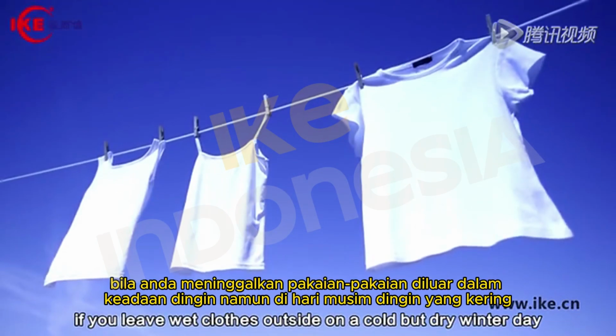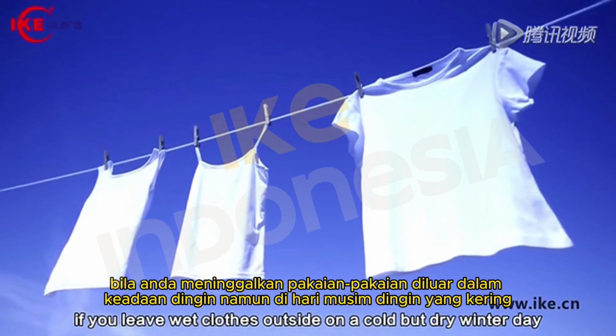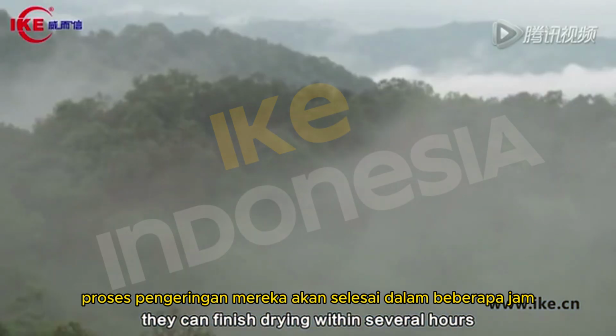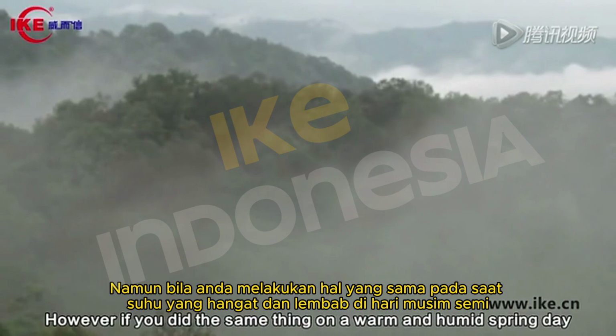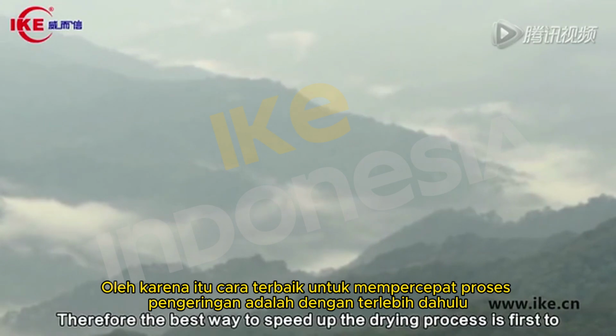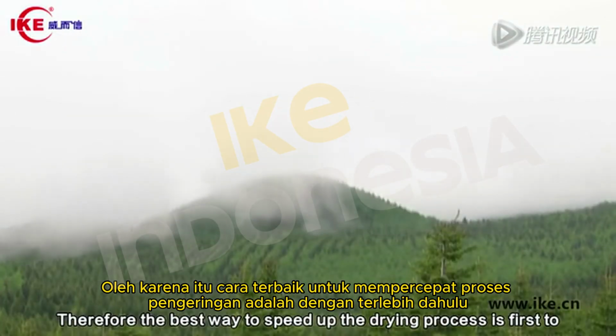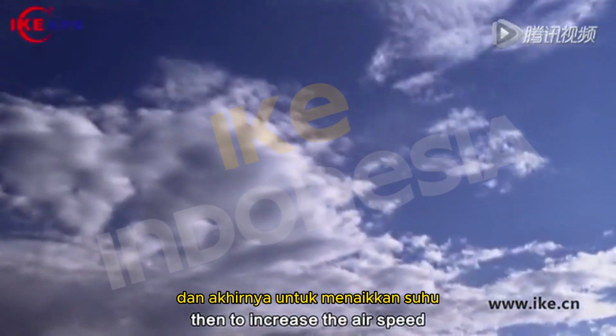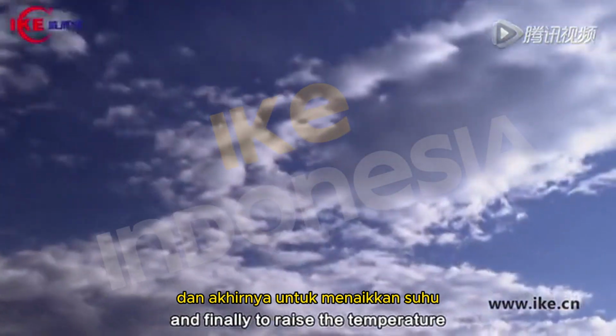For example, if you leave wet clothes outside on a cold but dry winter day, they can finish drying within several hours. However, if you did the same thing on a warm and humid spring day, they will still be damp even after several days. Therefore, the best way to speed up the drying process is first to reduce the relative humidity in the air, then to increase the air speed, and finally to raise the temperature.